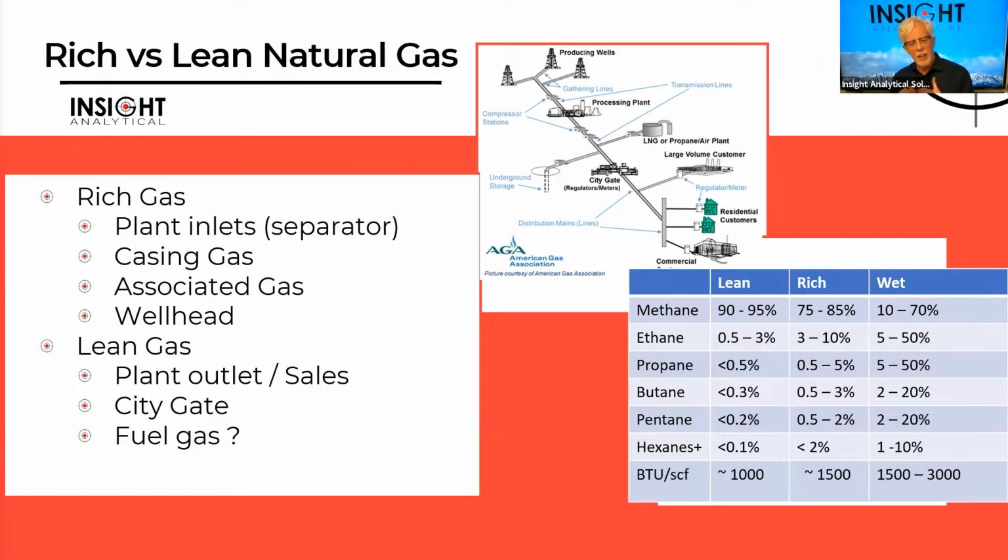They have a lot different oxygen demand for how much air is needed in order to burn them. And so if we're trying to run burners on, say, a variable fuel, which might be a blend of some of the lean gas we're buying from a natural gas producer or pipeline, and some perhaps gas we're producing at site, rich natural gas, casing gases, wellhead gases, these can have a lot of variability, and it makes it more difficult to control burners. And that's where things like feed-forward control analyzers to do full burner control become important.